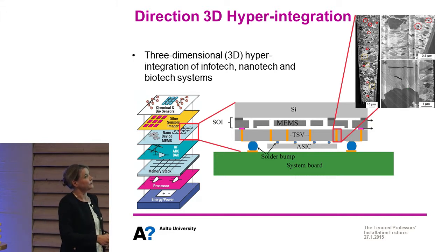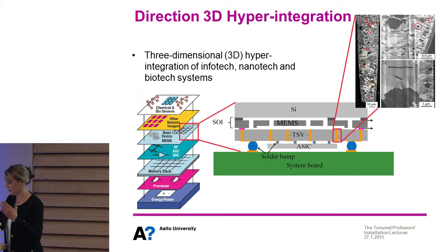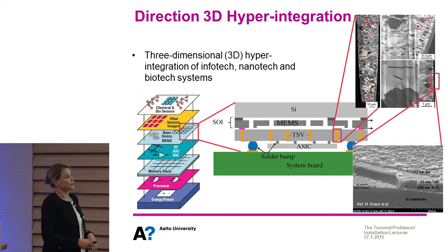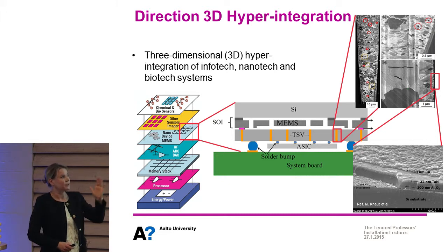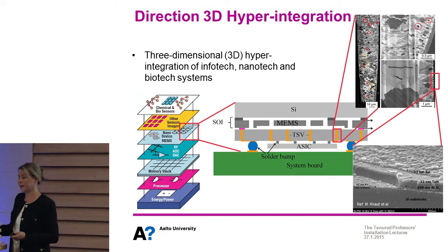It looks like this. This is a copper filling, so there are etched paths around 5 to 10 or 20 microns max, and going through perhaps 100 microns or more. And those, again, will have very delicate structures. We will have all the isolating structures and diffusion barriers and so on included underneath.